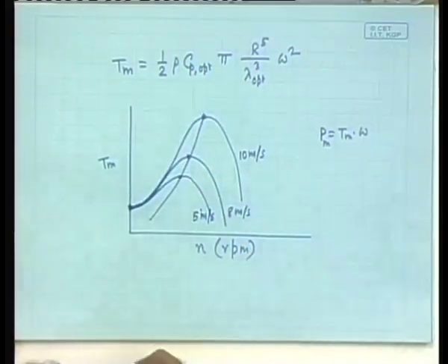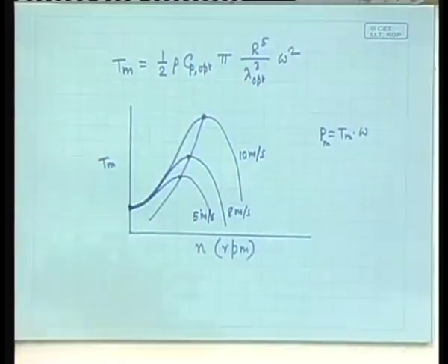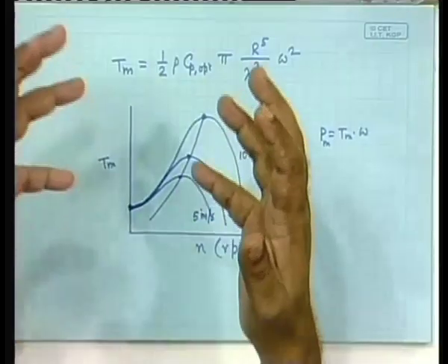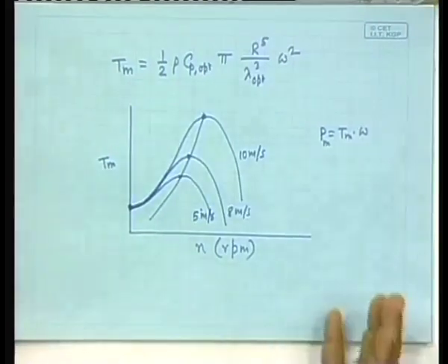Similarly, when you are using it as an electrical source, that means it is being converted to electrical energy, and that is supplying some kind of a load, then it will also have its own torque versus speed characteristics. Nowadays all these are mostly not directly connected; rather they go through some kind of a power electronic interface through which it is possible to control the power and hence the torque.